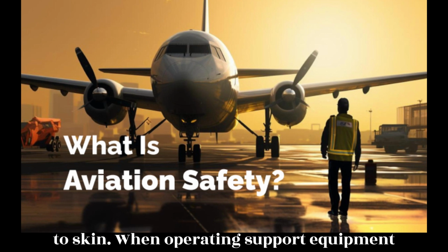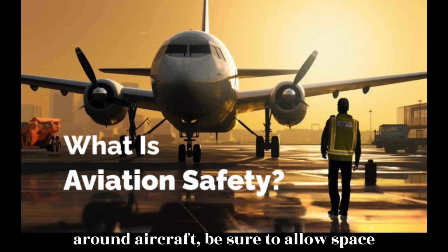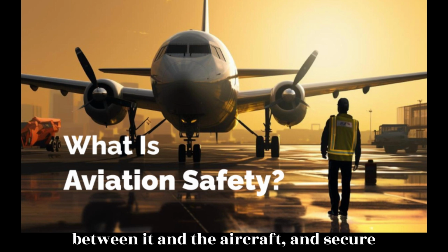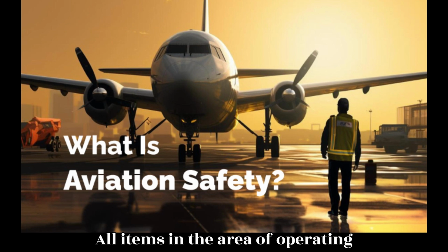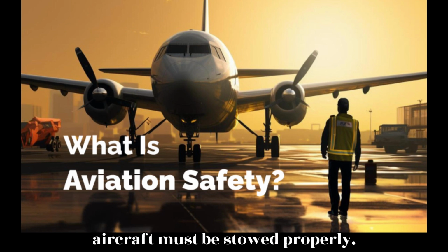When operating support equipment around aircraft, be sure to allow space between it and the aircraft, and secure it so it cannot roll into the aircraft. All items in the area of operating aircraft must be stowed properly.